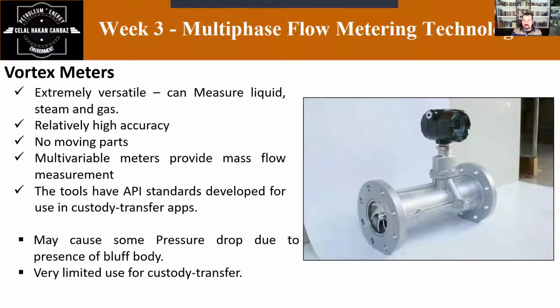Flow measurement is performed based on the vortex principle. Inside each vortex flow meter, a bluff body is located in the middle of the pipe. This body is a kind of obstruction that disturbs the flow, and the vortices are present on either side of the bluff body and are carried away by the flowing fluid.